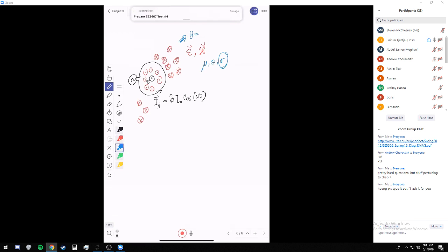So the impressed current is the current that you purposely put in, and this current will generate the magnetic field. The magnetic field, because it varies with time, in turn also produces an electric field, and the two of them are related. Then if the medium has conductivity, there's some kind of current flowing inside the medium. That current flow is the one that consumes the energy or turns it into heat. Does it make sense?